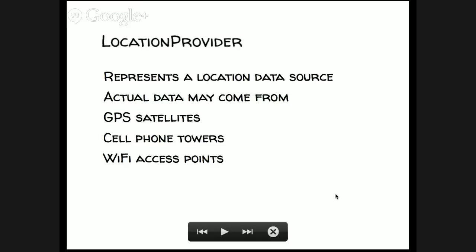And then for every cell phone tower, I can hear this tower, I can hear that tower. If you circle around this region, if I'm hearing B at a signal strength of some value, I could be at this much distance from B. And if I'm also hearing A, then I could be at this much distance from A. And then I also get C, I can be at this much distance from C. And so on.